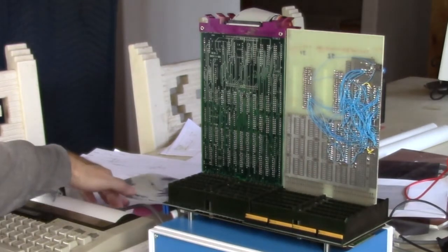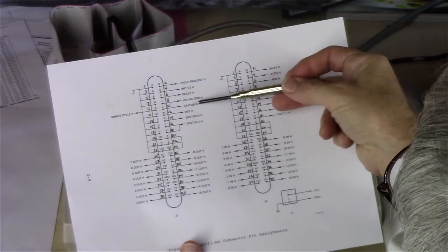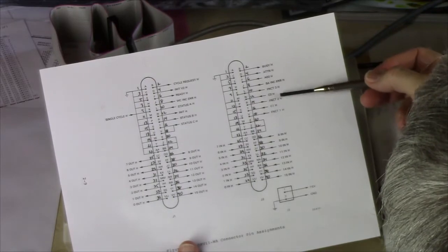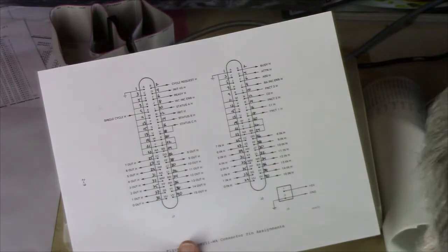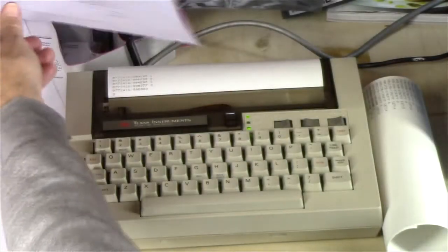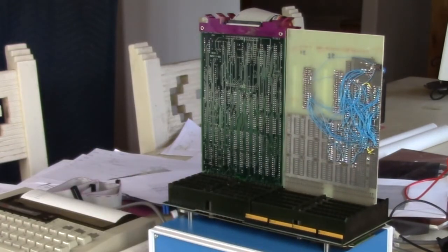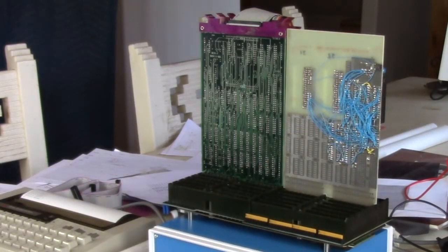It has three status lines: status A, status B, status C. So that just comes in as status A. By the way, there's funct1, funct2, funct3, which were those control lines, and the in and the out lines, and none of the rest is being used at this point. So that's what that button's for. That can be a little attention signal, if you have your program checking that bit to see if the button is pressed.